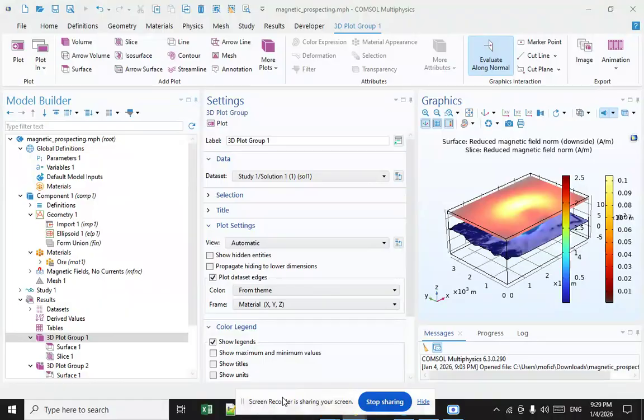Magnetometers used in geophysical survey may use a single sensor to measure the total magnetic field strength or may use two, sometimes more, spatially separated sensors to measure the gradient of the magnetic field, the difference between the sensors. In most archaeological applications, the latter gradiometer configuration is preferred because it provides better resolution of small near-surface phenomena.